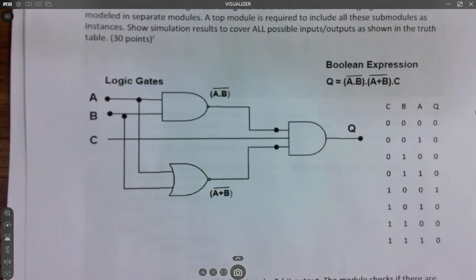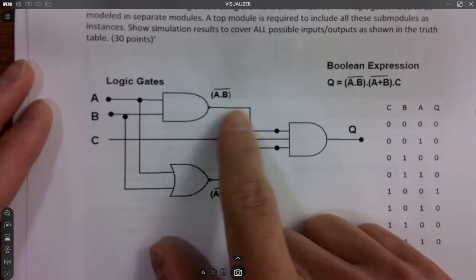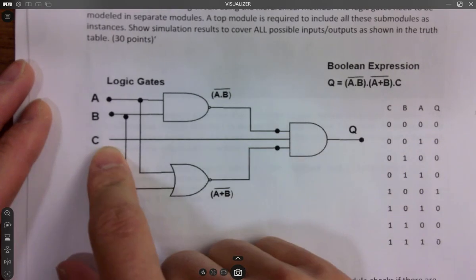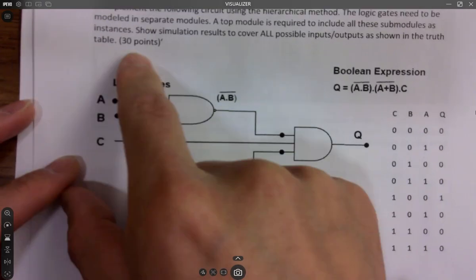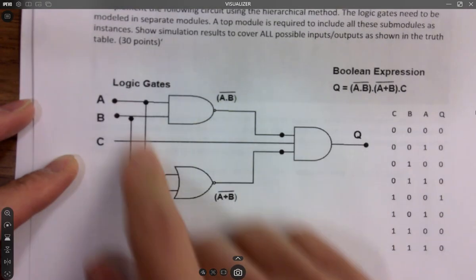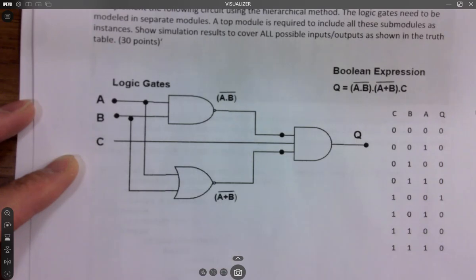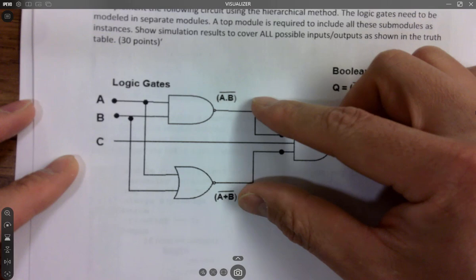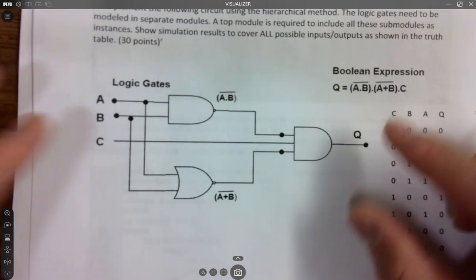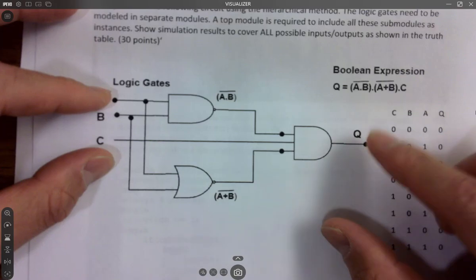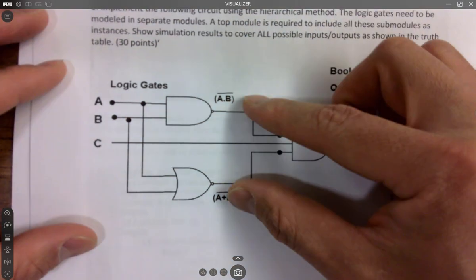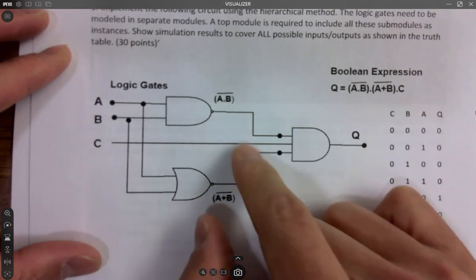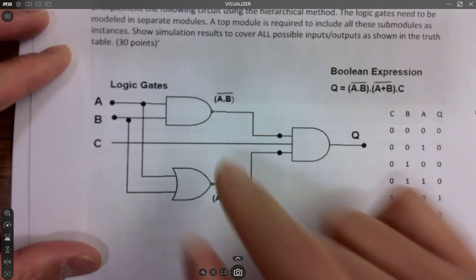So in that case, you can imagine, I have three wires, and the middle wire is shorted to the port. So in your top system module, you don't really need a second or third wire here. You only need two intermediate wires for the internal signal connections, and all the rest are just ports. So in your top system, you need two wires. Why not three wires? Because the third wire is shorted to the port, so you don't need this wire. You know what I'm saying?